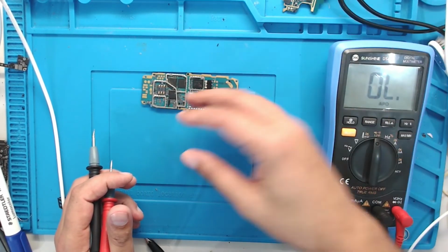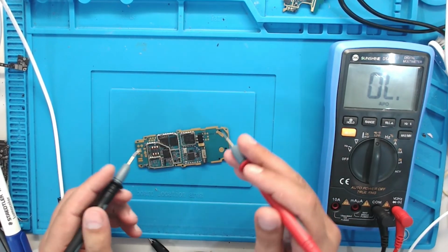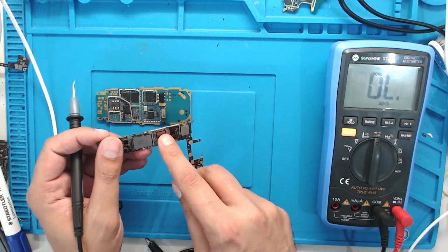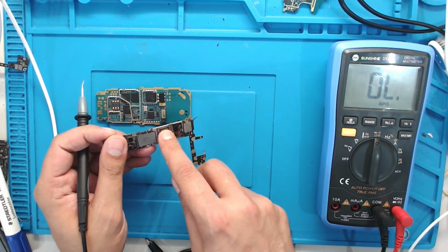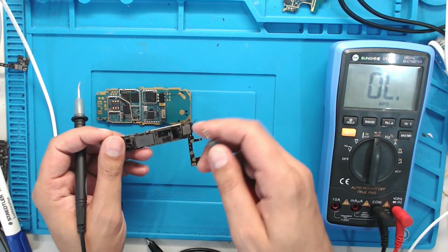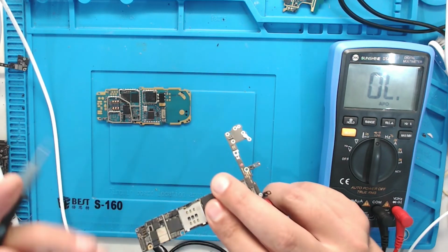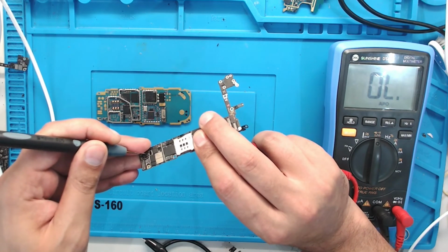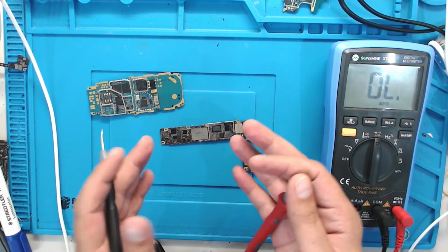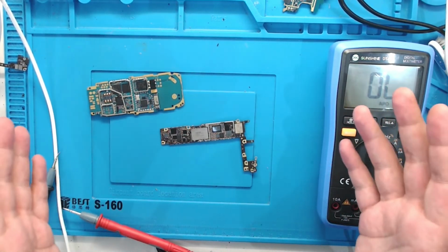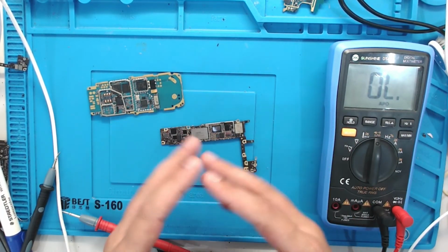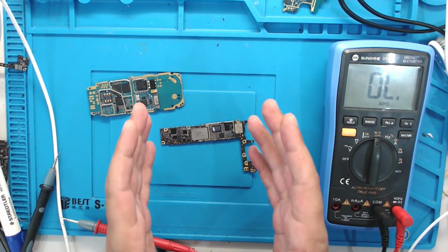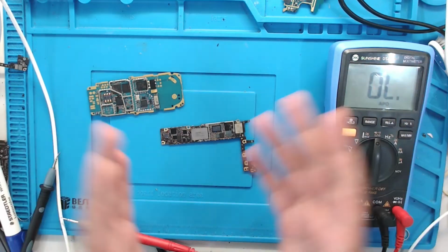But with some phones, which you check, that means before checking this phone, I know this capacitor shows 4 volts before pressing the power button. I put the cable in there, and you see when you put it on the positive side, it doesn't beep. That means this phone, very simple, has a two-side main voltage, and you need to find the charge IC, because the charge IC divides the main voltage to two sides.